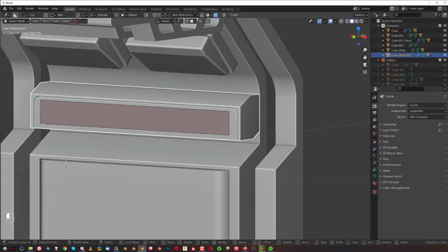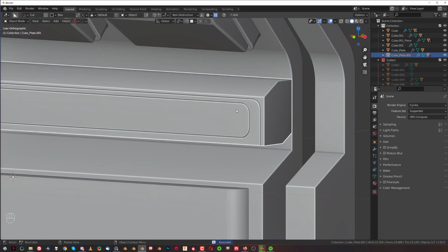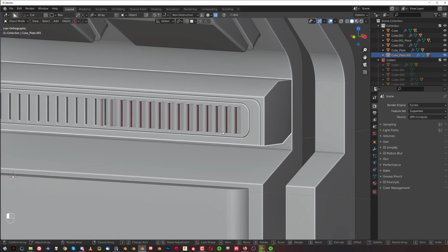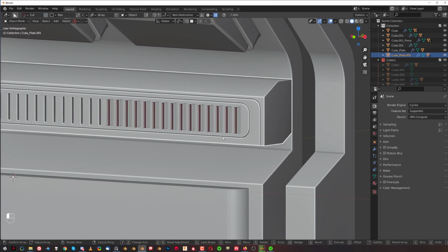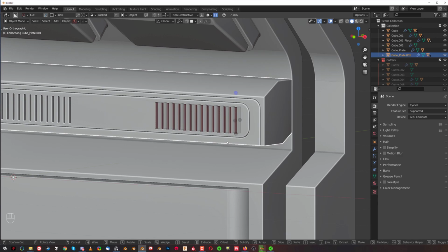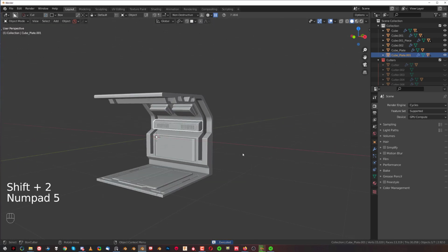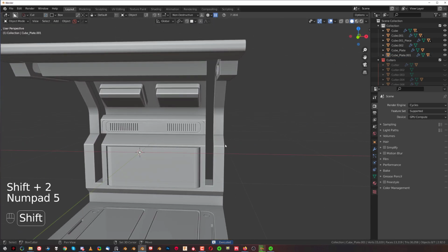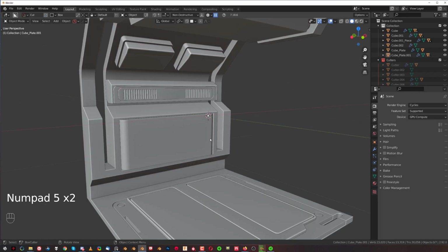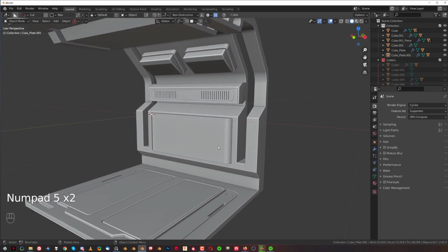We're going to make another cut inside of it, also with the bevel and T. And now we can create some kind of a pattern in here. So let's Shift R to reset the HardOps array, and let's array this a little bit on each side like that. Okay, cool. Yeah, that's better. See, it's not so loud, but actually fills in this area here.